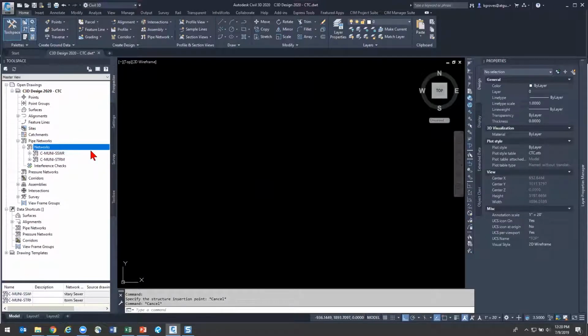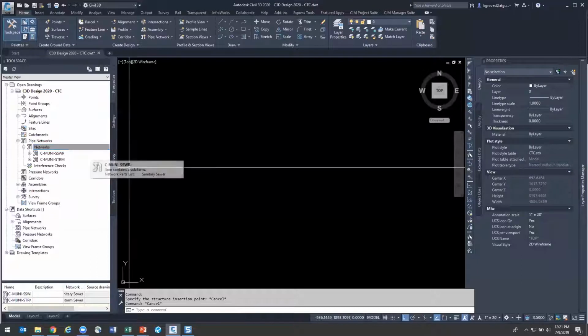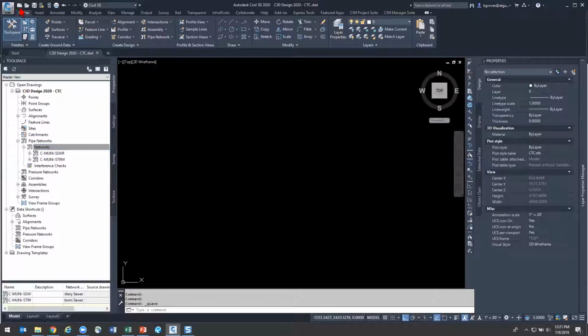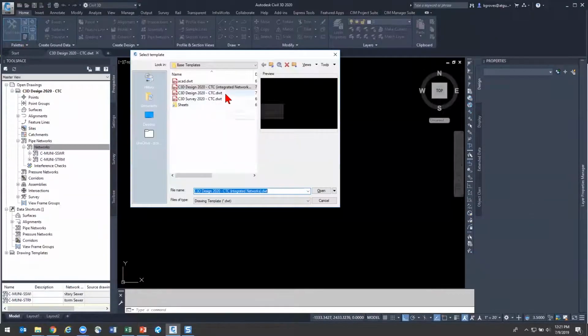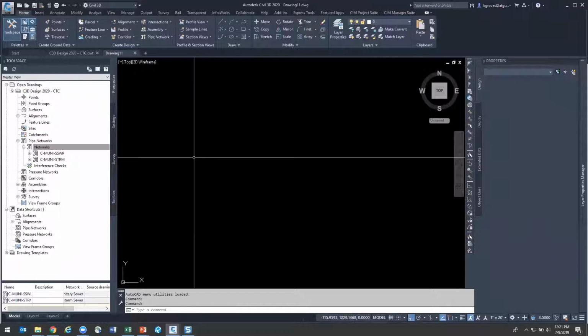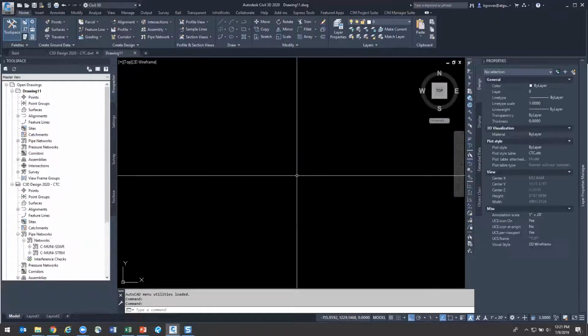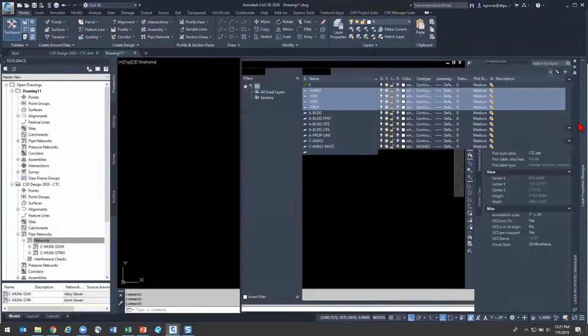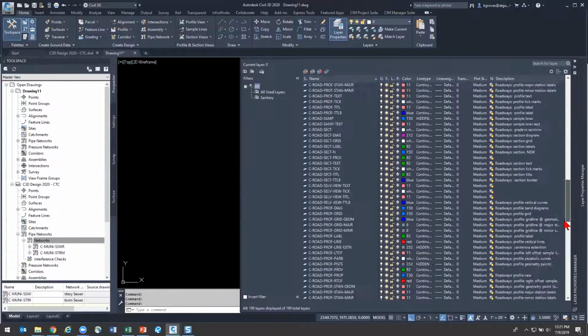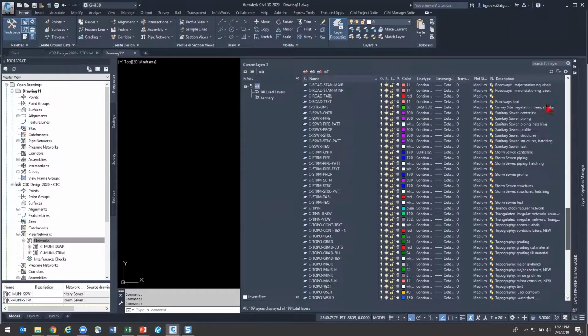And at this point, I'm ready to begin testing. And as I mentioned earlier, I'm not going to do that in my template. So from here, I'm just going to give this a save, and I'm going to create a new drawing based off of that, and here's where I'm going to go through and create my objects and make sure that everything is done. Now, since this came from that old drawing, notice that I have my pipe structure and profile stuff, but I do not have anything